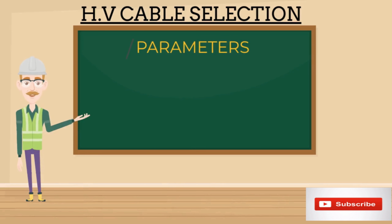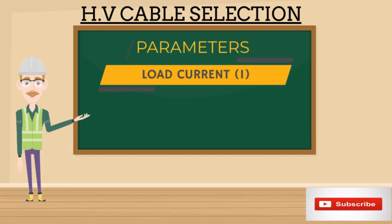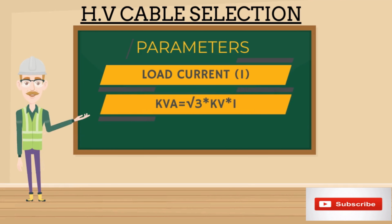The main parameter is the load current required to flow through the cable. Here, first we need to find out the load current required to flow through the primary side of the transformer. We can use an equation to find this out. The equation is kVA is equal to root 3 into kV into I, where kVA is the capacity of the transformer, which is 500 kVA, which we found out in our previous video, and kV is the required voltage in the primary side of the transformer, which we found out in our first video.